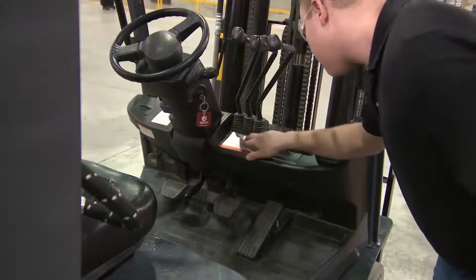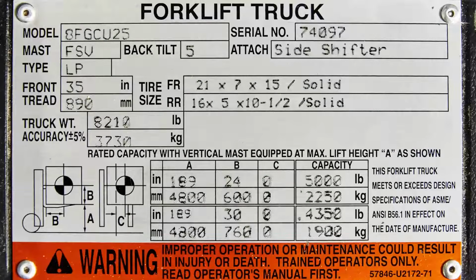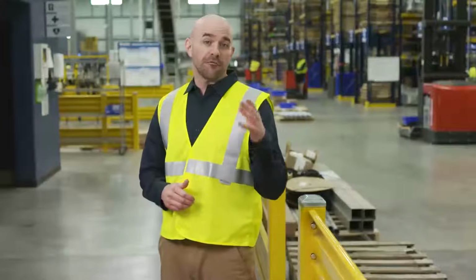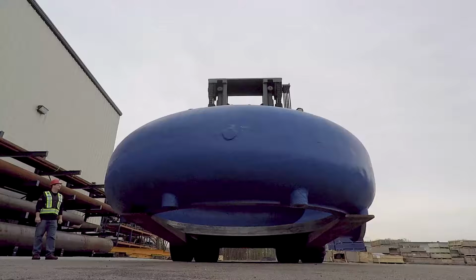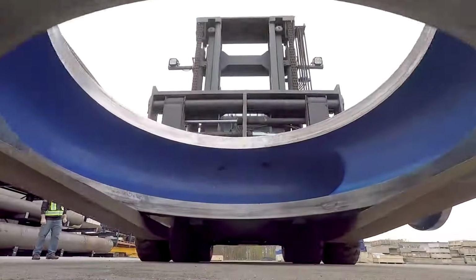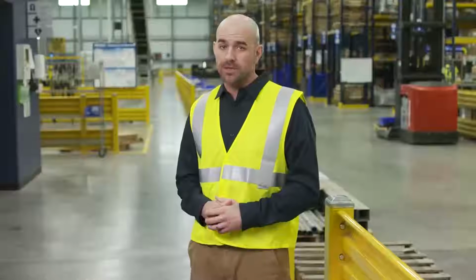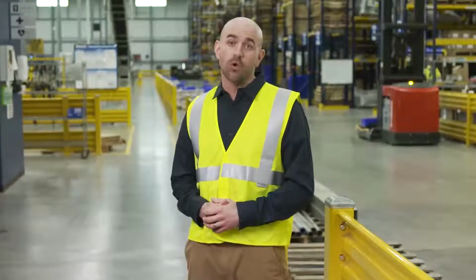Every forklift is required to have a data plate. It may also be referred to as a nameplate, capacity plate, or ID plate. The plate matches key information, including the model and serial number of the truck, the weight of the truck, and its load capacity. Verify every load to be sure it's within the rated capacity of your forklift. Here's a quick tip. Off-centered, irregularly shaped, or oversized loads significantly reduce the forklift's listed capacity and stability. Don't rush and wind up on the floor. Check with your supervisor when you need to handle oversized or irregular loads, especially when they're near the maximum listed capacity.